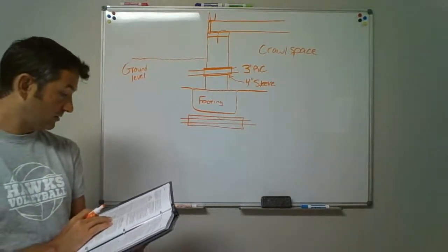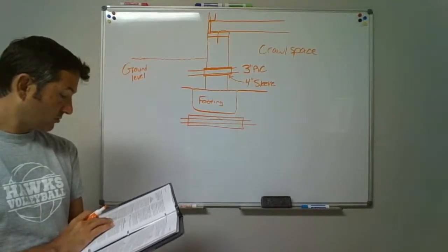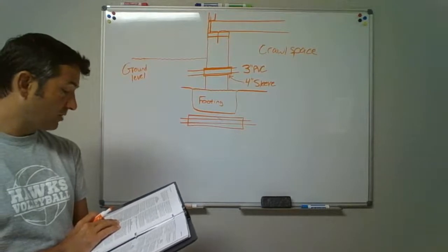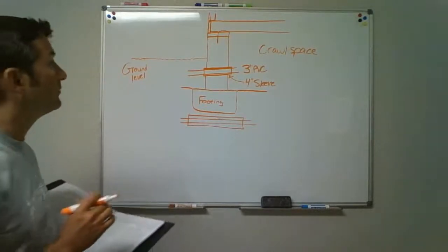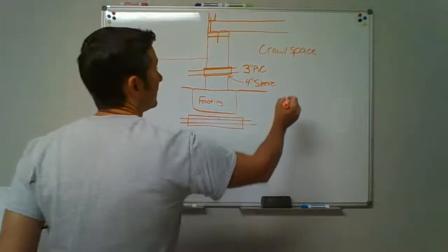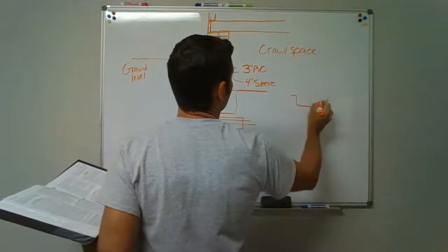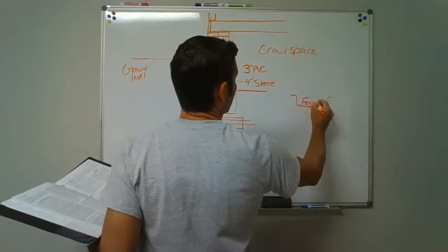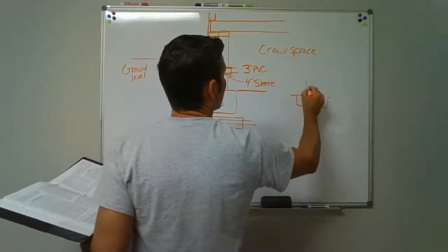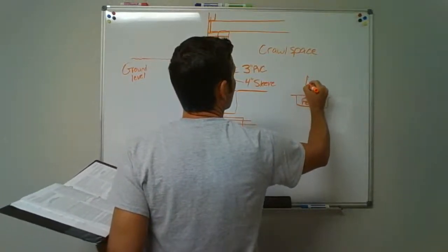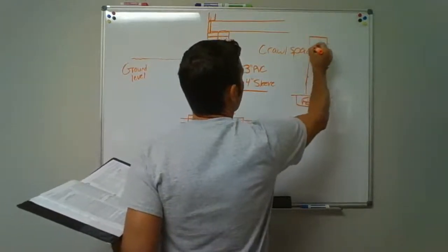All right, let's go back to 305.3. That's where it was. It also says that piping shall not be run under pier footings. So on the inside here, if they pour another footing or footer, so that's concrete across in there. And then they're making this coming up, and they just block that.